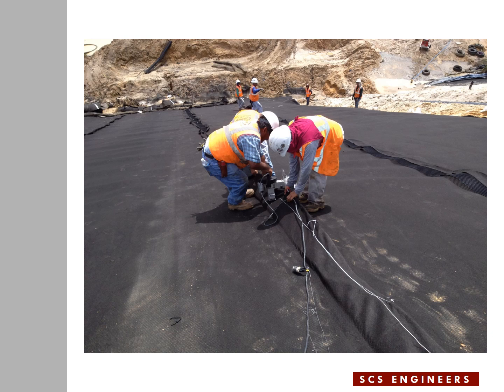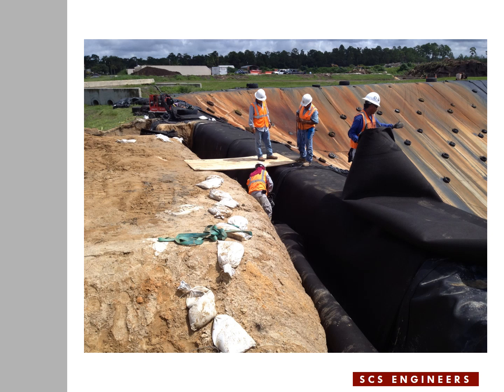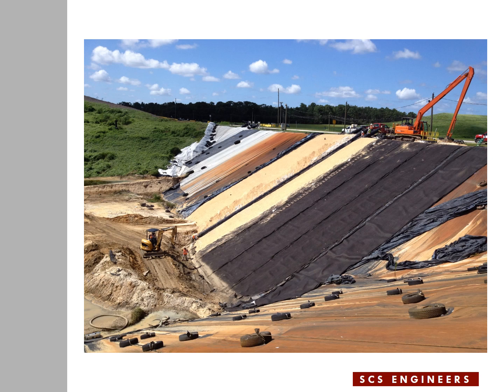The panels are tied together using plastic ties, and the geotextile components get sewn together. As I indicated earlier, the geocomposite goes into the anchor trench at the top of the slope. This is a view of the repair area after completion of the geocomposite. Geocomposite is tied to the existing composite at the bottom of the slope, and anchored in the anchor trench at the top of the slope.